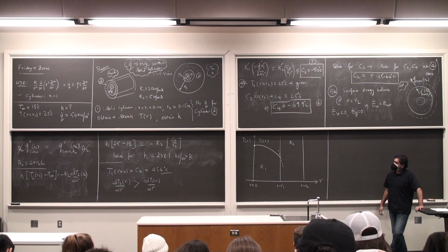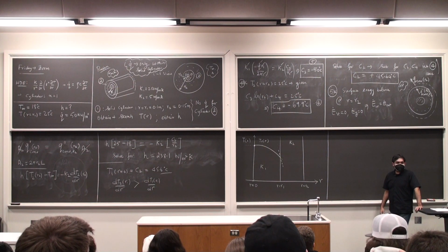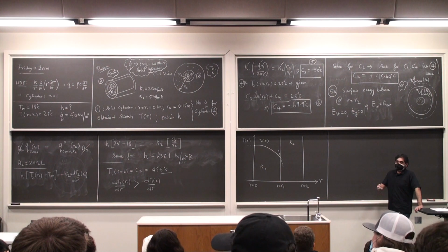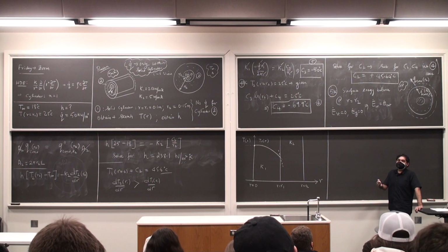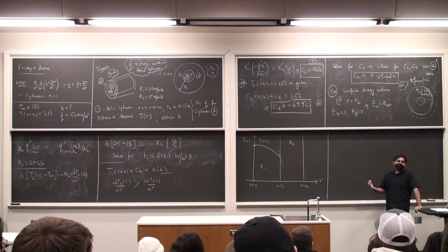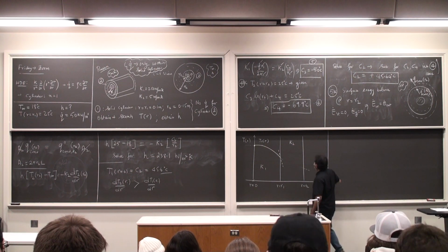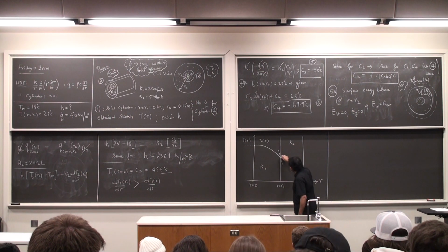Now the question is, do I go concave or convex? It's fairly straightforward. Just calculate the slope at R equals R2. Because the radius is higher, your slope is going to be C3 divided by R, and so the slope there is going to be lower than at R equals R1. So the manner of going is nonlinear because it's a logarithmic decrement.